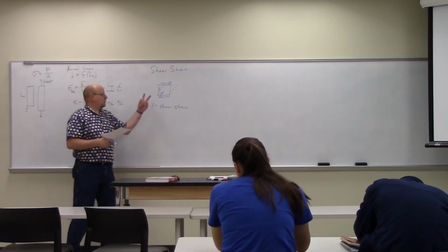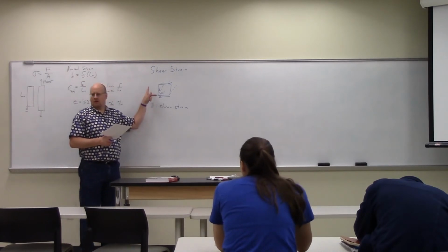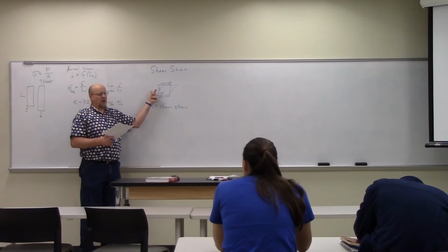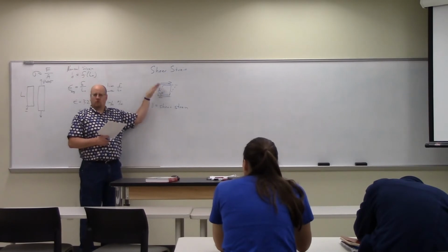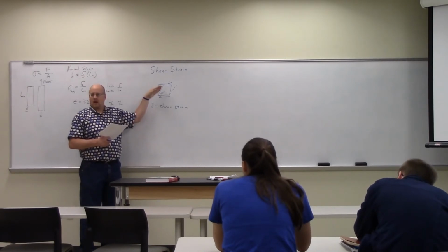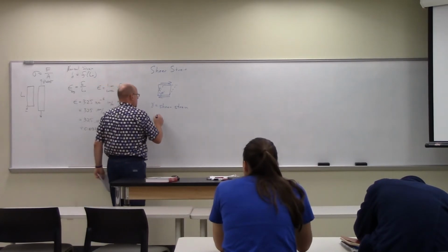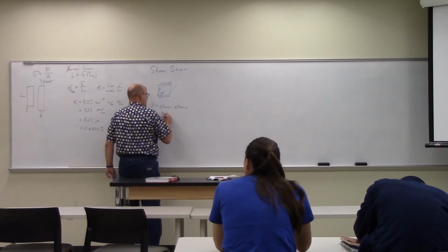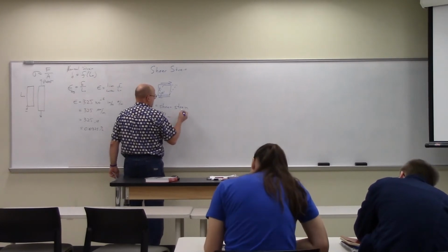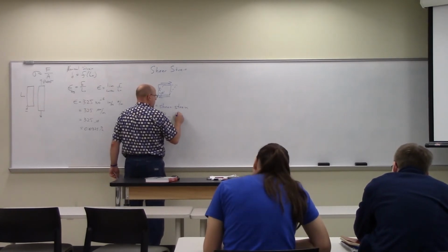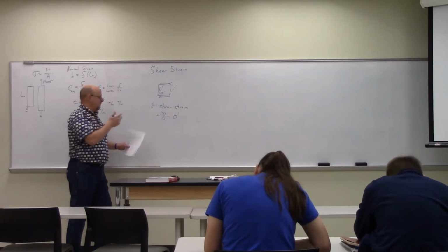See what I'm saying? Because you start with something that's a right angle, you know it's a right angle. When you end, you can't say how much did it move. What you do is you measure the residual angle that's left, and then subtract it from the 90 degrees that was there to begin with. So in reality, we often do this as pi over 2 minus theta prime, for average.